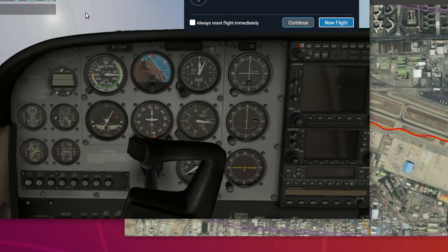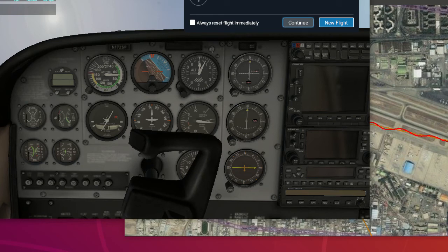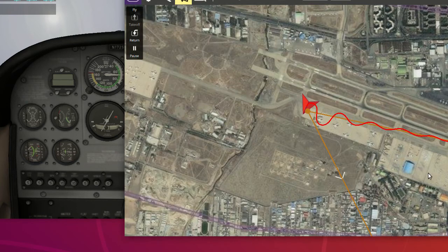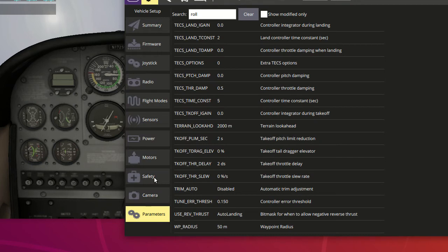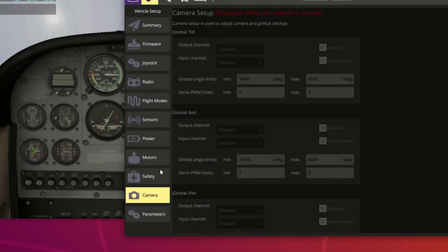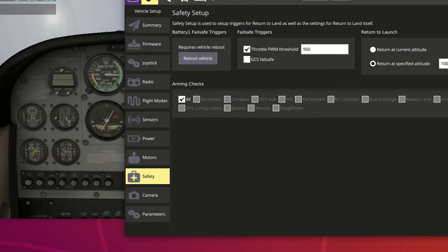Okay, this is the hardest method for software in the loop simulation with X-Plane. As I told you, there is a very simple form. If you are not going to change anything and have a normal purpose, you can use the way it's built into Mission Planner. Go to Mission Planner, and in the simulation tab you select X-Plane and just click on the plane. Everything is done. You only need to install X-Plane and do the configuration I told you about here. When you click on the plane, suddenly everything is done and X-Plane is connected to your Mission Planner.